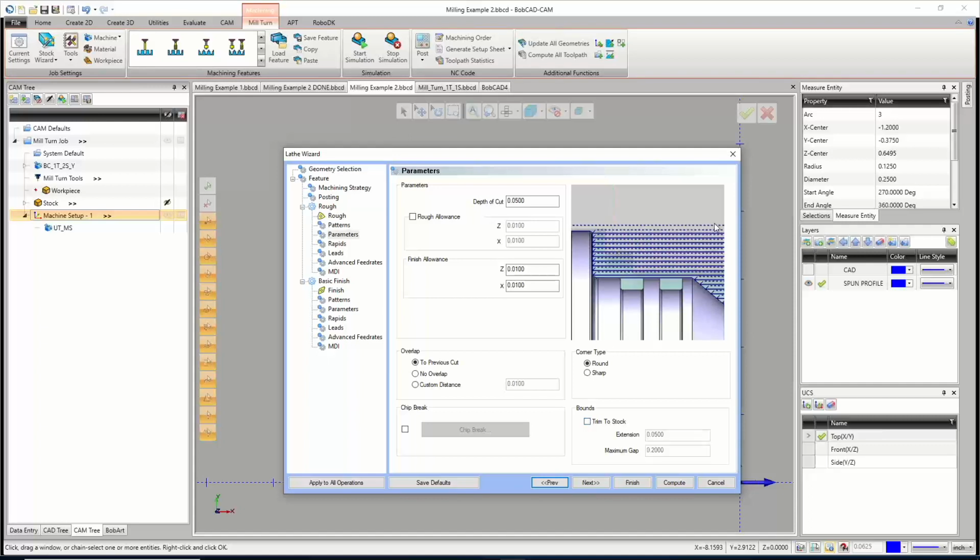So normal cuts would look like this. We're wasting all this time cutting a bunch of air, where if I set my stock up properly, it'll trim to where it actually sees the stock. Great option, but a lot of it entails you having more information, usually another piece of stock.